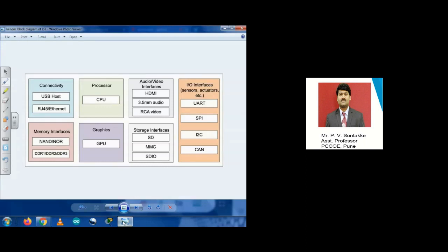Differentiation points between all these serial communication protocols. Again, the pin indicates what? It means how many devices can be connected, the maximum possible devices in a bus, because it's a kind of serial communication bus. UART, SPI, I2C, CAN, these are the kinds of buses used for exchanging data from one device to another, or one controller to another controller, isn't it?